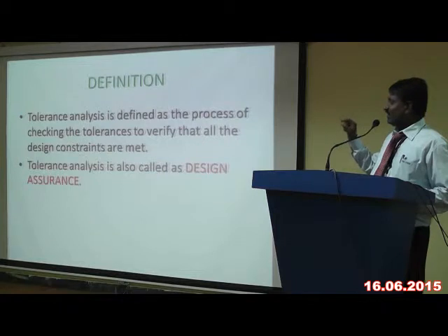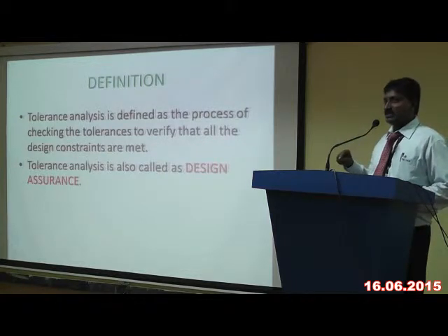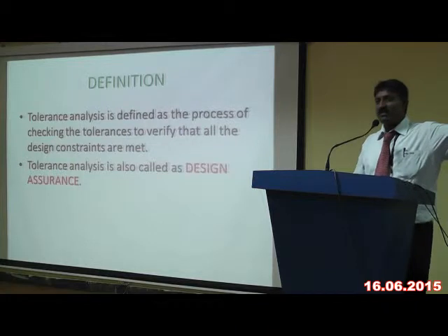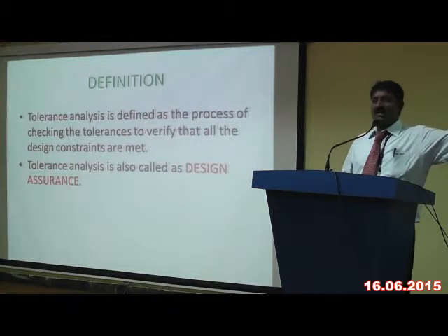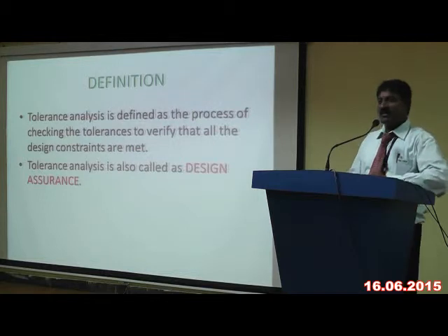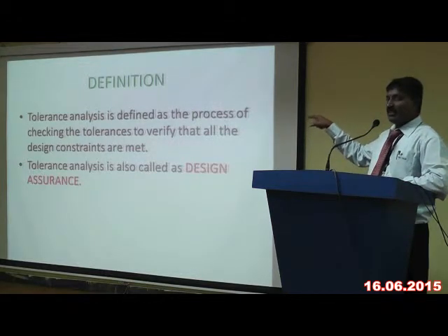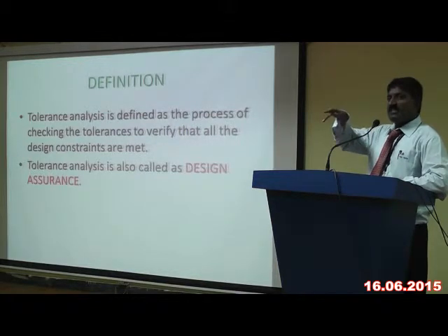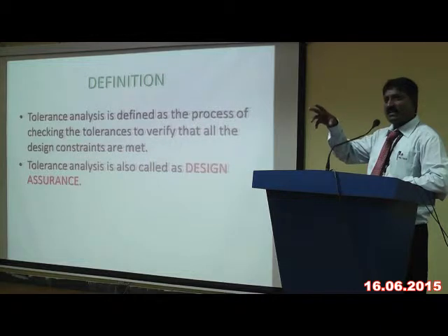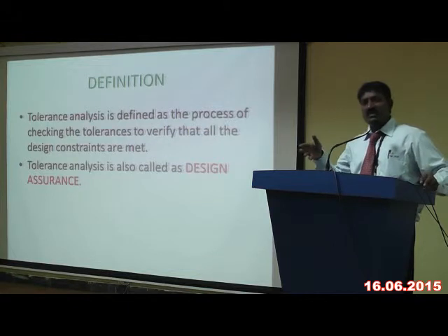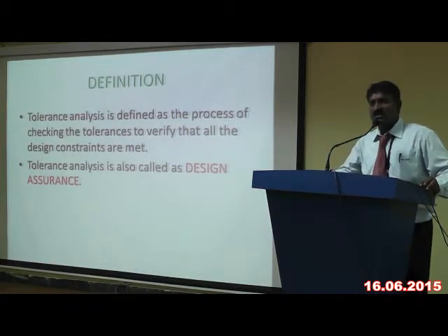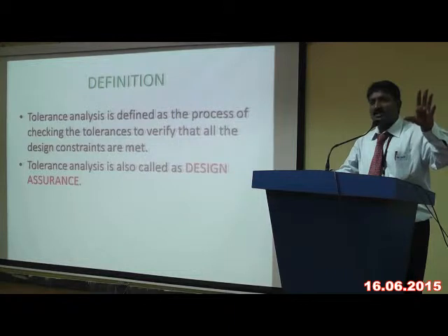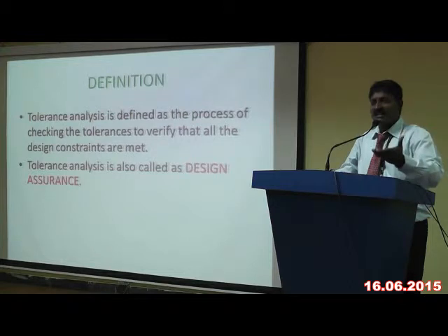Tolerance analysis is defined as a process of checking the tolerances. Already we have learned what the tolerances are and what kind of tolerances should be given, and from there to verify. We are going to verify and analyze whether this is correct or not, because a lot of bad samples are there, individual samples are there. I am manufacturing per shift about 300 components in the same CNC machine I have programmed, and out of 300, about 250 are okay and 50 are getting rejected.